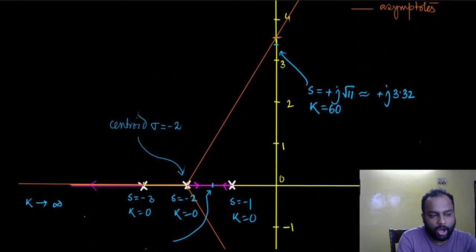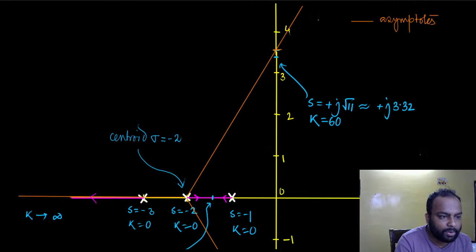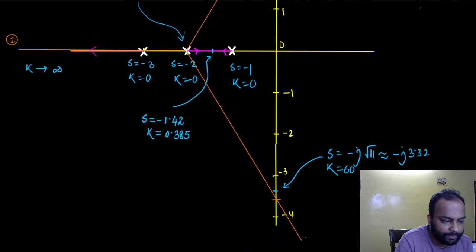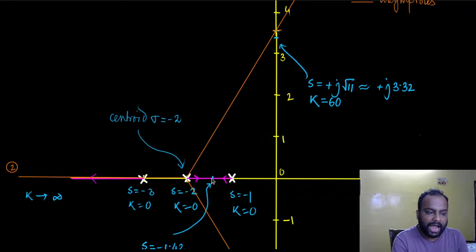And now we also confirmed by our theory that the asymptotes are tangents at infinity for the root loci. So essentially, the roots would follow the asymptotes. Let's say this is asymptote number 1, this is asymptote number 2, and this is asymptote number 3. Already this root, that was the pole at s equal to -3, as gain increased, is following asymptote number 2. And the other two roots, after breaking away from this breakaway point, should also follow the asymptotes.